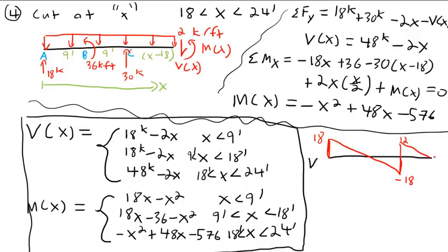So yes, you might ask, how can you have a discontinuity in a function like that? Well, remember how we talked about how point loads really can't exist? This is why a true point load really can't exist, because then you end up with a discontinuity in the shear and moment. Now, that's fine for our models. As a way of designing beams, this works perfectly well.